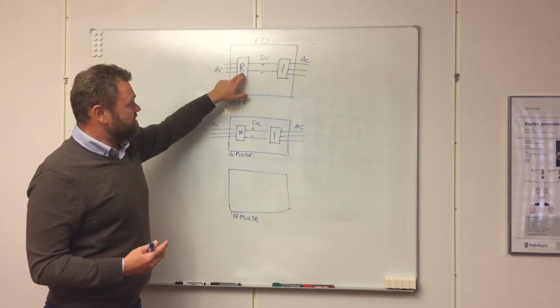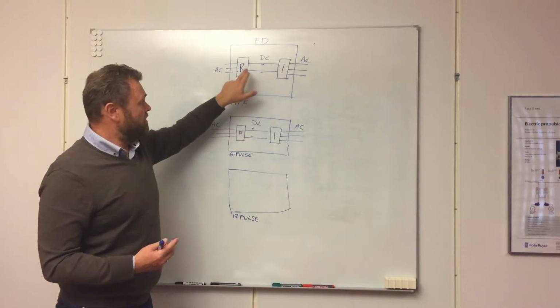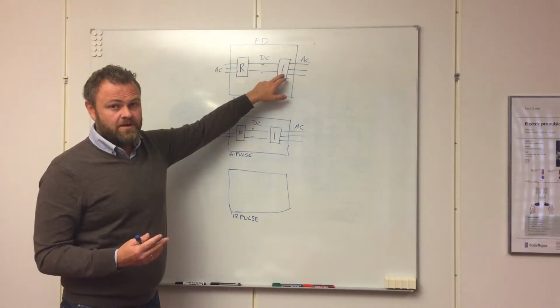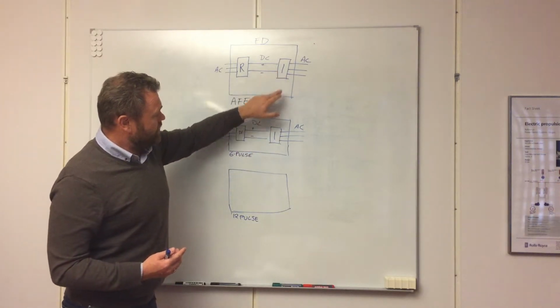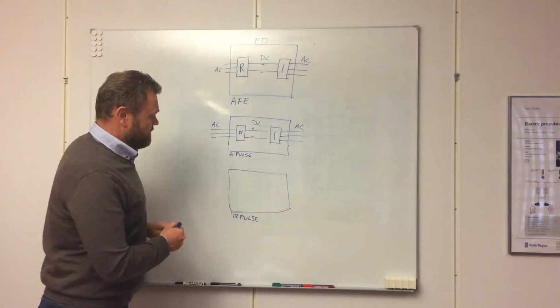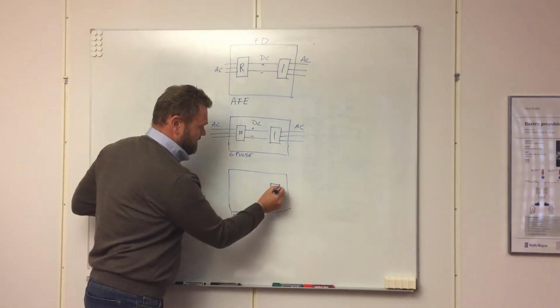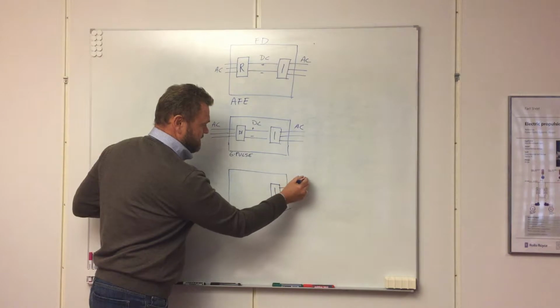This is more or less the same component as this one. More or less the same. The hardware is normally typically the same. And the inverter unit is the same for all solutions, because we need the active IGBTs to be able to produce AC.